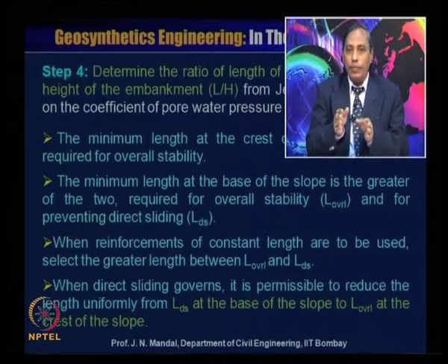So, these are some points given by Jewell, and this will be much clearer when I give one example related to the steep reinforced soil slope. We will see how we can make use of the design chart given by Jewell and how the length can be selected based on direct sliding and overall stability.